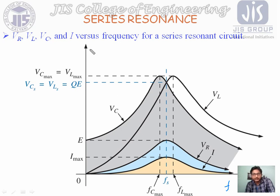We consider the voltage across the inductor and the voltage across the capacitor, plotted separately. For frequency versus voltage across the capacitor, we get this graph. Whenever we increase the frequency, the voltage across the capacitor increases, and after a certain value, the voltage decreases again.